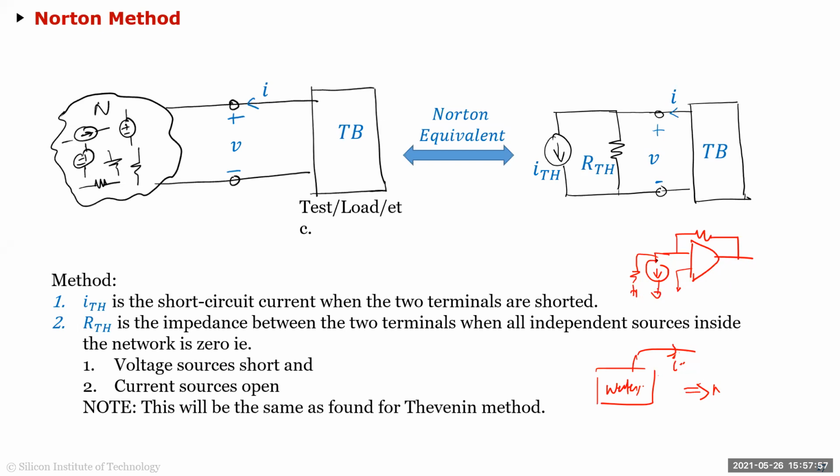But here you actually get the current directly, and what is your output impedance. So it's more natural to that system. So yeah, it depends on the system. So if your output is current, usually you would like to do a Norton equivalent of this. If your output is a voltage with a very low impedance, then you do Thevenin's equivalent.